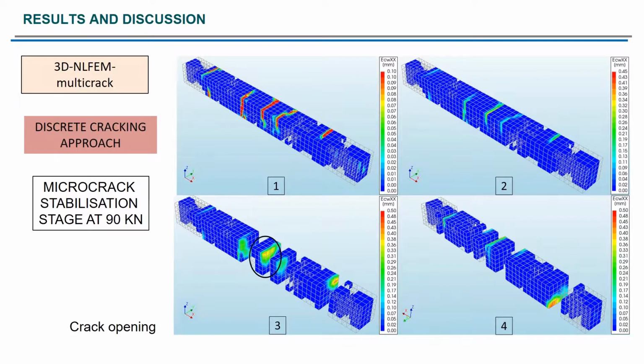In the following slide, I'm now representing the crack openings in the longitudinal direction. All 4 figures represent the same property, but with different scales or views, and we can observe 2 main effects. The first one is that the crack opening varies along the specimen. It's not a uniform distribution. And moreover, if we see the detail across the section, the crack opening does not reach the whole section. This can seem weird, but it is due to the random field that was used in the characterization, and it's quite similar to what we usually see in the experimental test.